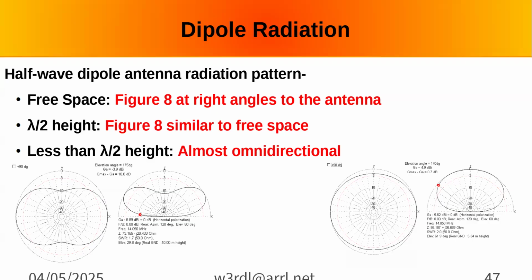It's very important. Military uses the hell out of it. It allows you to get over a mountain at short distances, a few hundred miles. With normal propagation, you can't talk to somebody 200 miles away. You're going to bounce right over them. You can with NVIS.